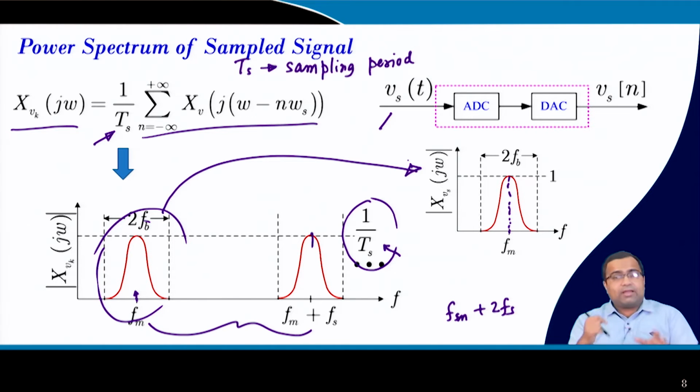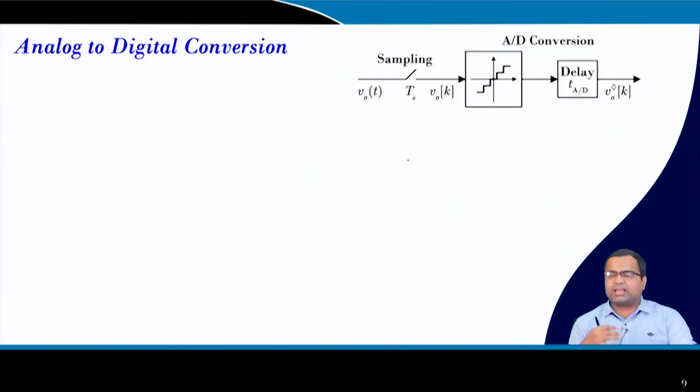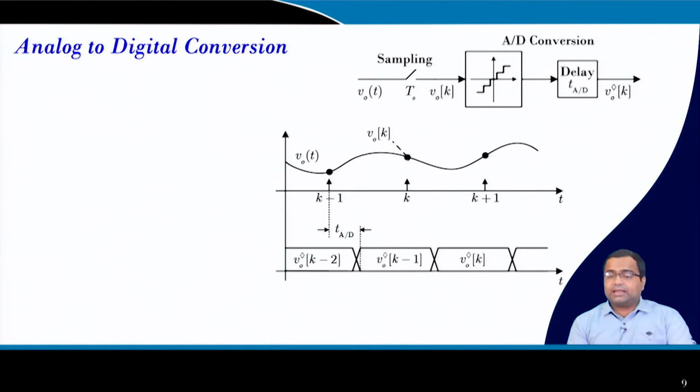So, now why are we studying this? Because in our switching converter we need to decide the sampling rate. Now, going back to the analog to digital converter, in our DC-DC converter we have the output voltage. In fact, this is our sense voltage, where we could consider the gain of the sensor, but for simplicity, let us assume it is the output voltage, and we need to sense the output voltage.